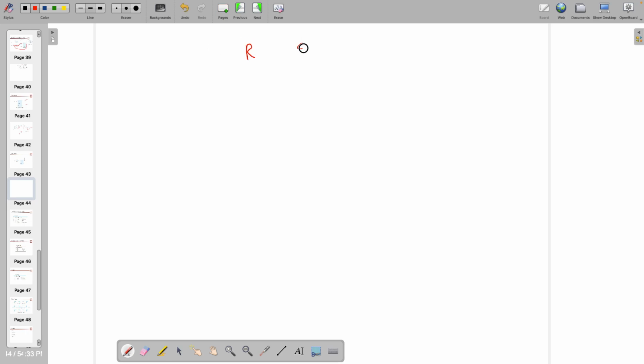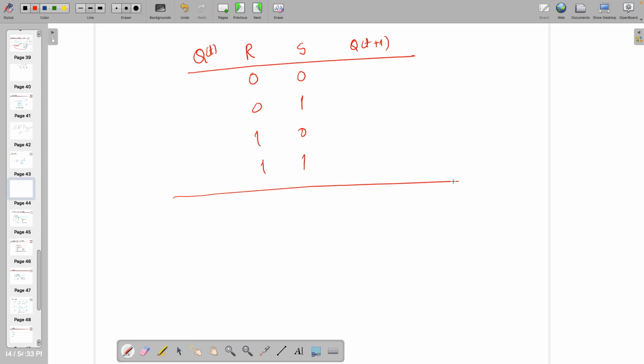How does it look? The RS latch is the one which has 2 inputs. So 0 0, I am talking about the NAND based RS latch where the 2 inputs are 0 0. What output am I expecting? It's invalid, because both the outputs are 1.